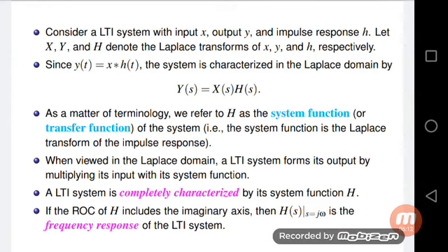If the ROC of H includes the imaginary axis, then H of s evaluated at s equal to j omega is the frequency response of the LTI system.